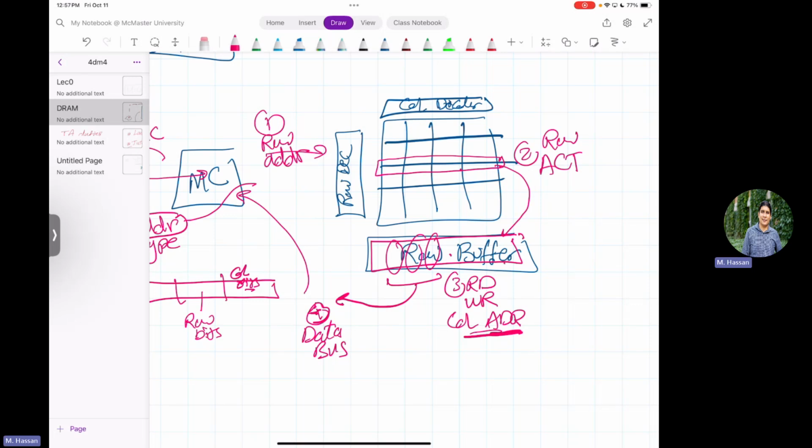Why do we do this? The main reason is, again, cost. You want to minimize the DRAM chip cost. One of the highest cost elements in any chip, and this is something we mentioned when we talked about control path and data path, do you remember? What did we say? It is the number of ports, like the number of pins in the chip. If you are in the chip design business, the number of pins is really what defines your cost. This is the highest cost element. So if you want to cut down costs, minimize the number of pins.